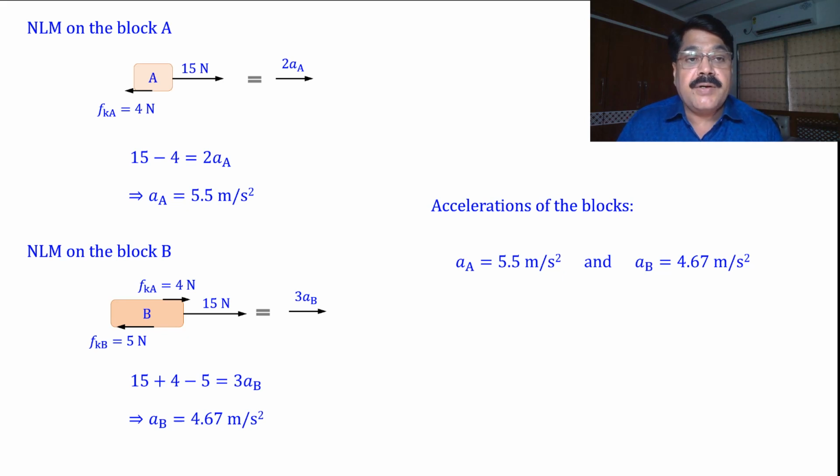Now the next thing is what? To decide the sequence of sliding. So at which surface we are to decide the sequence of sliding, or whether sliding will be there or not, what do you do? Assume there is a required friction to prevent sliding. Calculate that required friction. If that required friction is greater than the limiting friction, there is sliding. If it is smaller than the limiting friction, there is no sliding. Now we have almost a clear-cut idea of taking decisions and their sequence in this kind of problem, and we are well equipped to take some higher order problem. Let us discuss a 3-block problem.